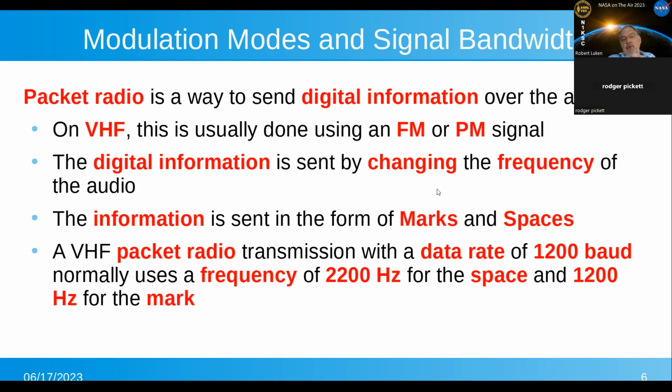Now, some of the newer digital modes, like FT8, for instance, which is one of the most popular ones, use 8 tones, 8 frequencies to represent a 3-bit combination, which has 8 states. So you're basically sending 3 bits at a time for every one of their characters.